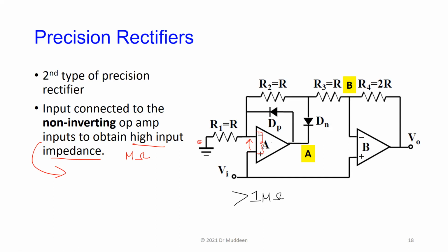And the better op-amps, the ones that, for instance, use JFETs or MOSFET inputs and so on, tend to have huge input impedances, which are in the order of 10 megohms to the gigohm sort of bracket, right?